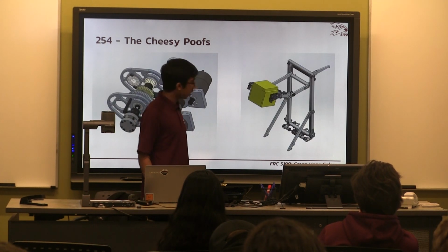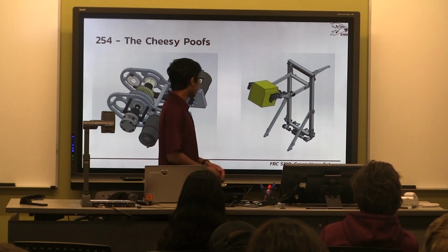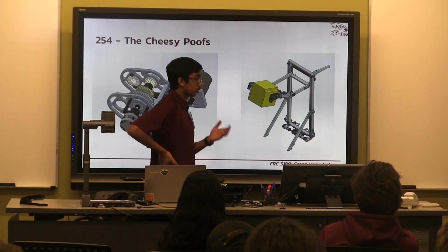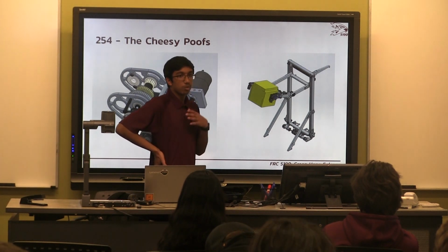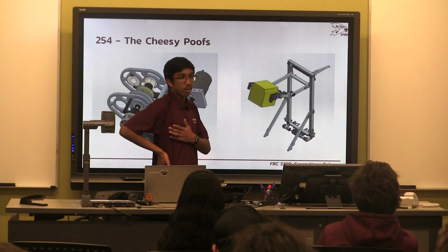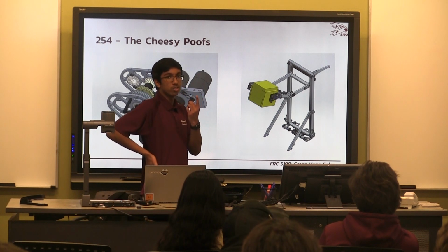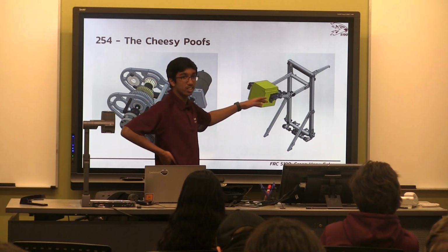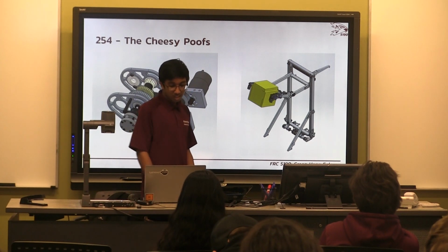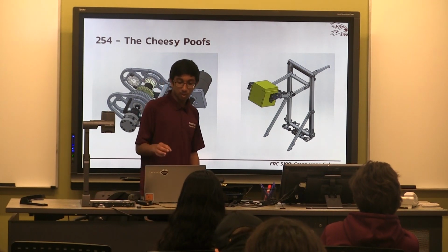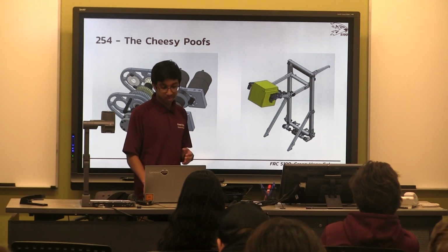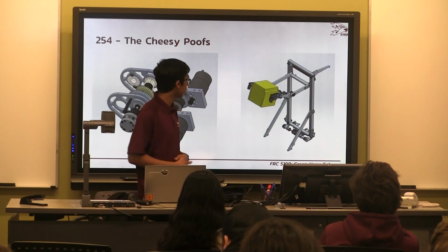So you can see here, these are the more final stages of CAD. You want to do a 2D sketch first, because anyone that CADs knows that if you figure out that one hole is wrong and you're this far in, it's a pain to change, since changing that one hole might affect a bunch of your other constraints. So you want to look at it in the 2D perspective before you go into a 3D perspective.